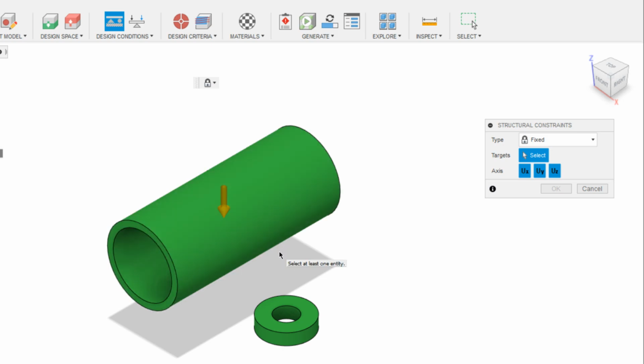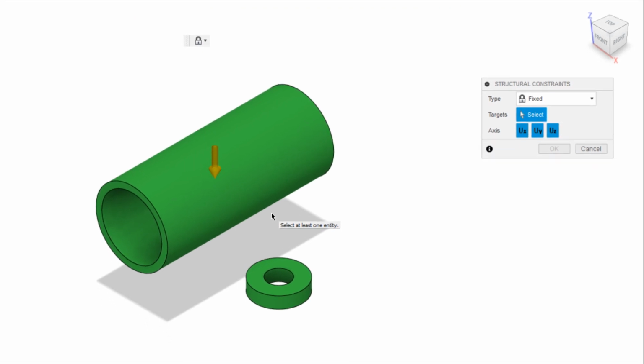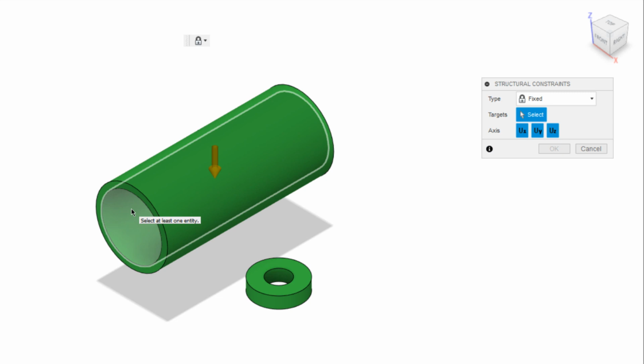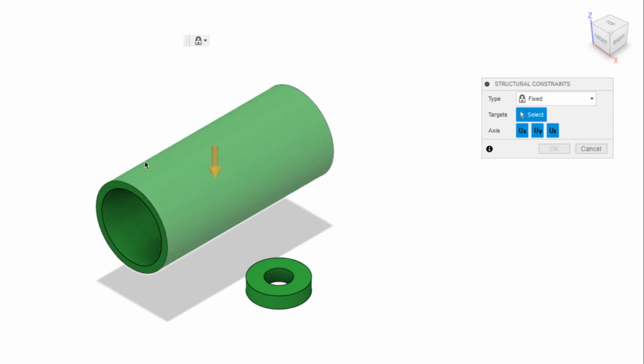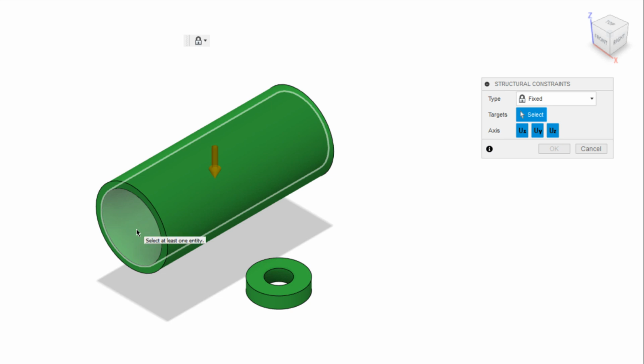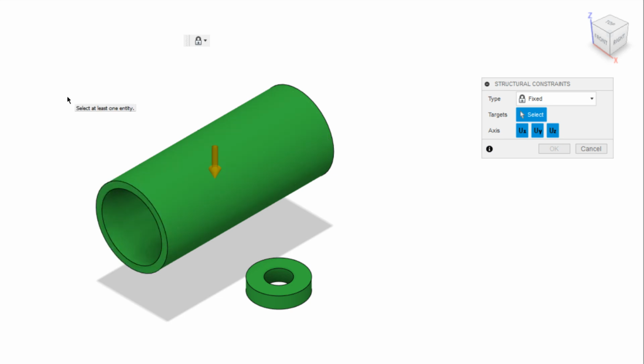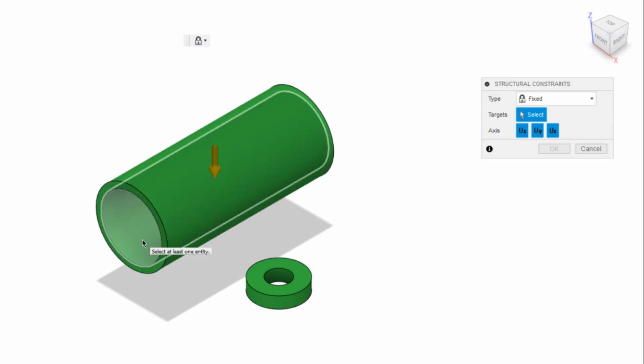In an ideal scenario, this bracket is mounted on the floor of an automobile, and the cylindrical shaft comes from the seat, and it goes from this end to this end. So when passengers sit, the load is going to act on the floor, but it won't act on the cylinder. When we brake the vehicle, the load of the passengers will act in the front direction. Similarly, when the vehicle starts suddenly, the load is going to act in the backward direction. So we are going to define those two load cases in this example.